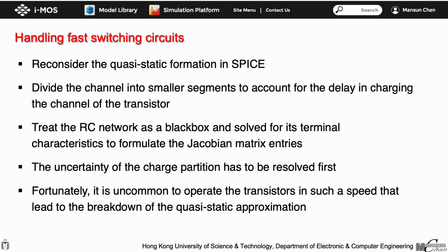However, the good news is, when the size of the circuit becomes bigger and bigger with many nodes, the nature of the circuit becomes more distributed, and the problem caused by the NQS effect may not be observable. But this is a very important piece of information to keep in mind as a model developer.